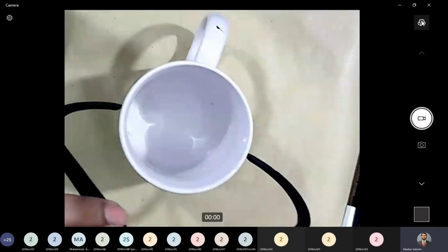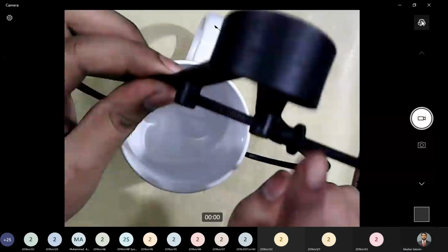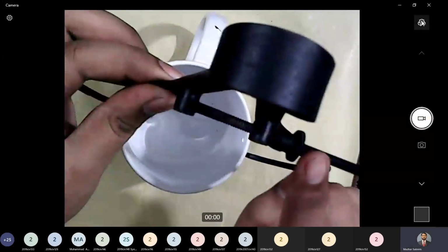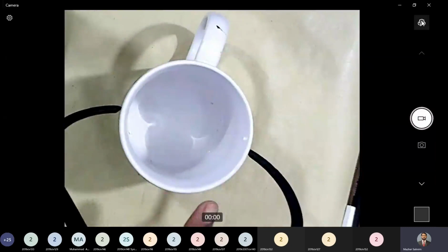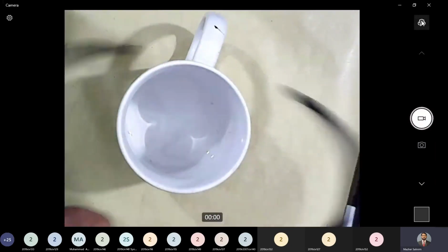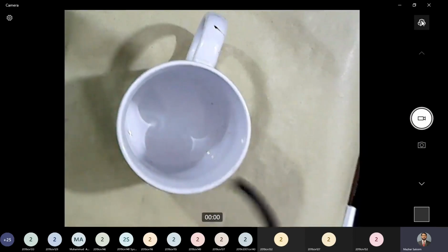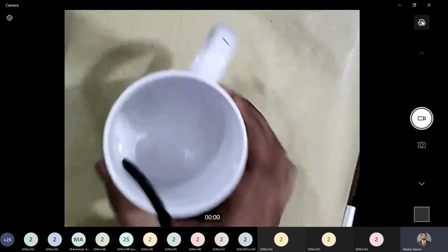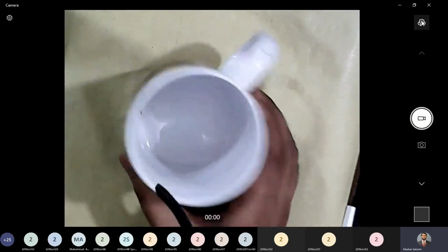Here, I have opened it equal to the external diameter, and using this screw here, I can ensure the caliper is opened exactly according to my requirement. I can just take this out and put it on a steel rule and measure this opening. So that will help us in measuring the outer diameter of this object precisely.